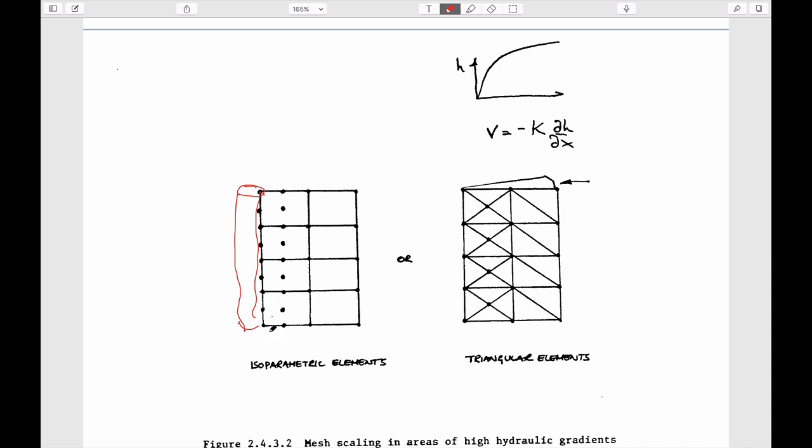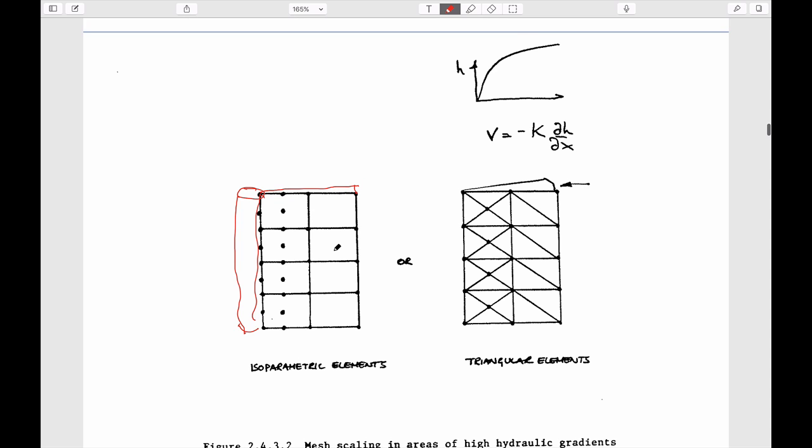We could get away by really just drawing basically a wedge of the cake. And the wedge of the cake would be what we'd refer to as axisymmetric elements. In other words, they repeat themselves as you go around. And so you only need a two-dimensional geometry to represent the behavior as you go away from the well.